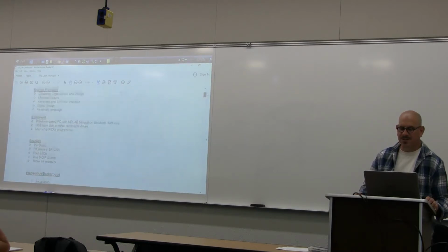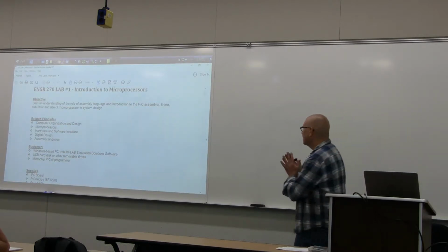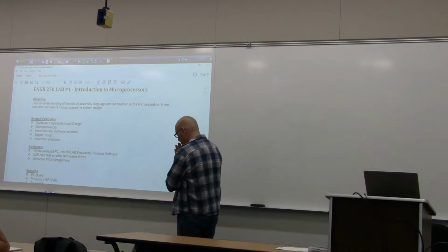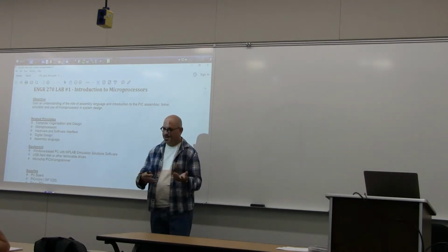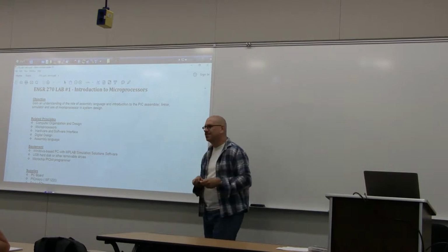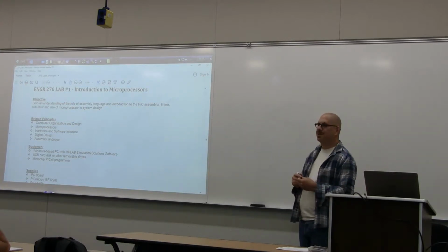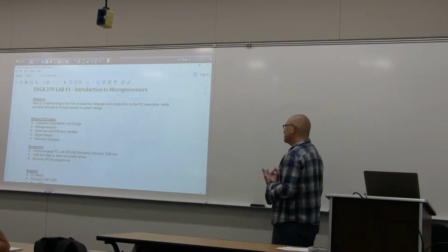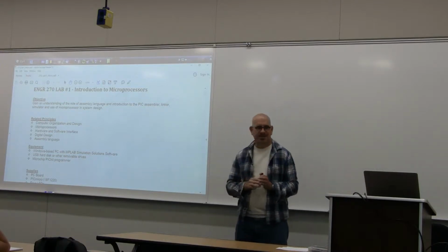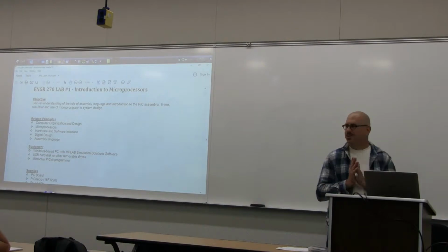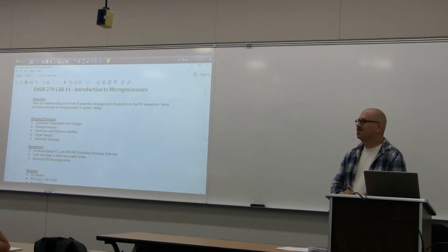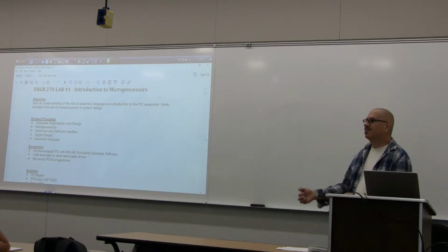All right, a couple of things that came up while people were doing labs on Tuesday. The first thing is sometimes you get everything wired up and you go through the software and you try to program your device and it complains about PIC-Kit2 not found or unexpected device error or something like that. In some cases those errors can be ignored. The ones about PIC-Kit2 not found seem to be ignorable as long as you can do the following steps.